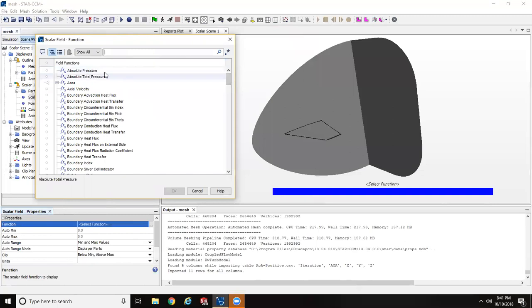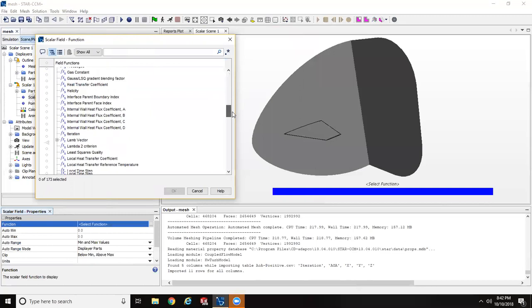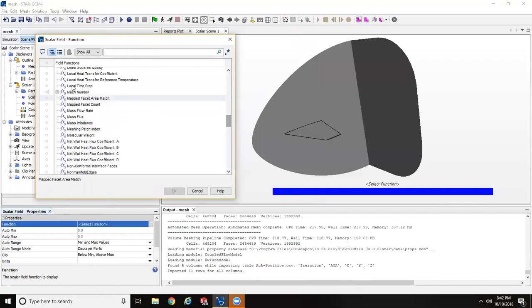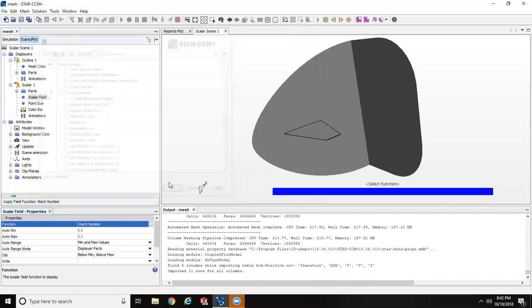These absolute pressures can be misleading. So what you like to look at is basically Mach number. So we can plot, and you click on that box and then click the lab reference frame. So right now that will plot Mach number.